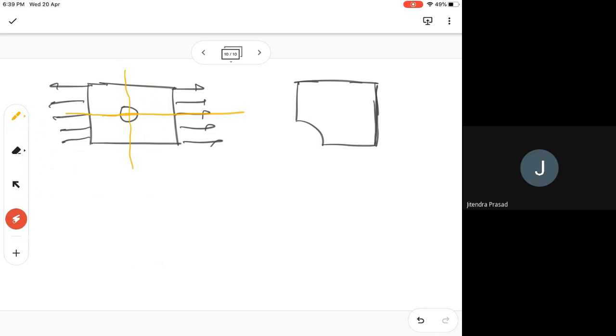So there will be no displacement in y direction in this case. This will be equivalent to a roller basically like this. Now regarding this, since you have the load going this way and this way also, the same force on both sides, you also see that this is a line of symmetry. There is no displacement here as well in both the directions. So you can also have a roller here.